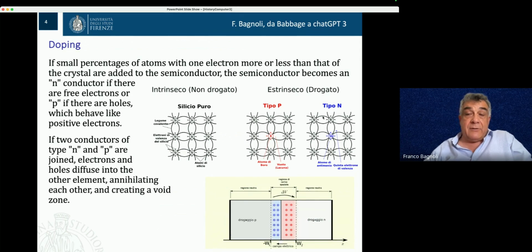On the other side, you have a lattice with some atoms replaced with another one with more electrons. So they have a free charge of type N, negative, that can travel. Remember that the lattice is anyhow neutral, so if you have a positive hole here that jumps away, it leaves here a negative charge, and vice versa in the other case.